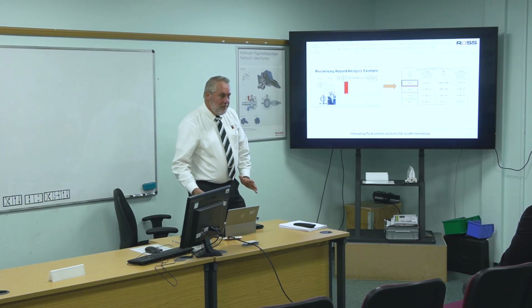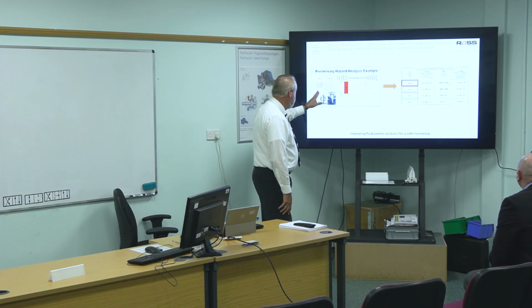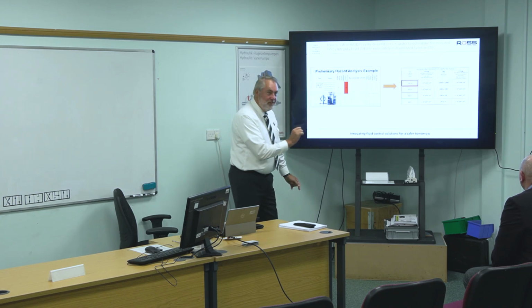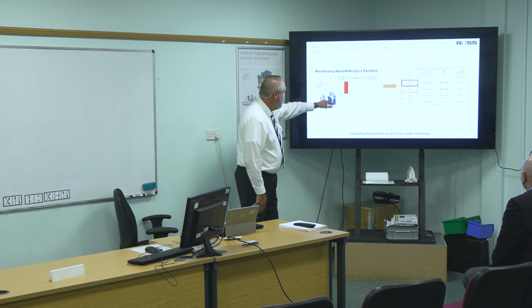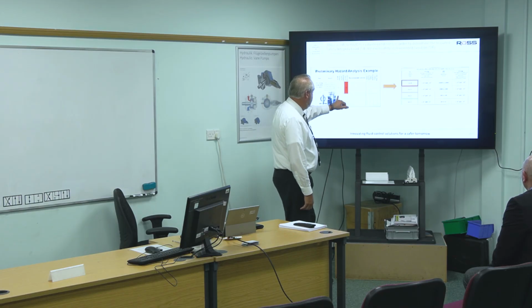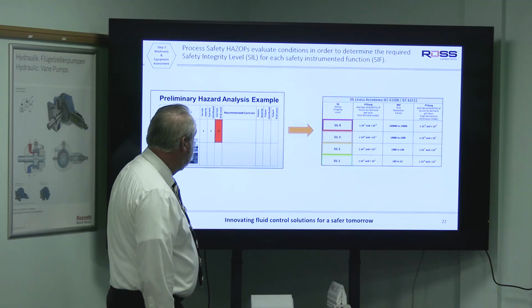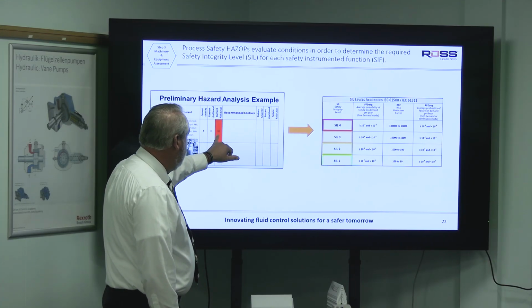Process safety is a little different. Process safety looks at what is the person doing. In this case, dosing using 100% SO2 liquid. So adding some liquid to the process. What is the health risk? And then what is the severity? What's the likelihood that they would actually be exposed to that unsafe situation? And then it gives you a risk level.